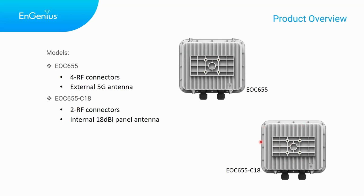There are two 5 GHz radios. That means one radio would work with the internal C18 built-in panel antenna. If you want to add an external antenna that would run simultaneously with this built-in antenna, you can do so as well. That would be running on radio 2. Now, with those running simultaneously, like I mentioned, they can be facing backward from each other, or you can have them work as a redundant link. Radio 1 and radio 2 would have high availability or load balancing as well.